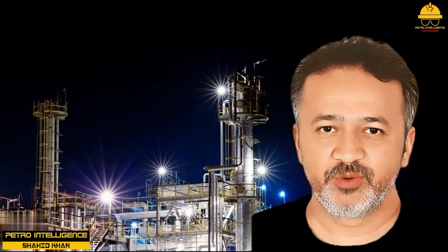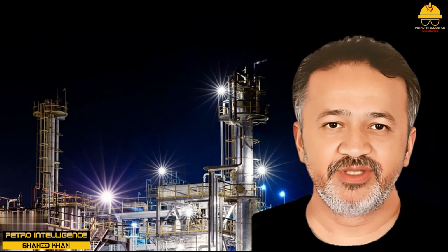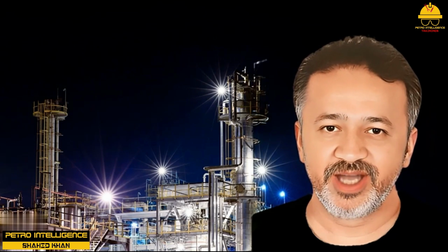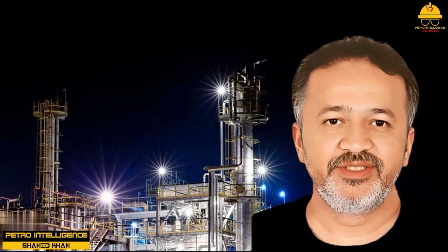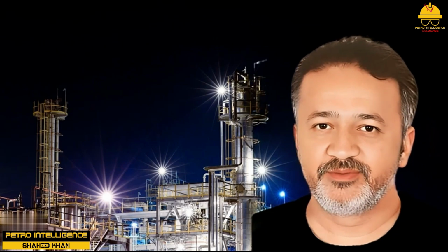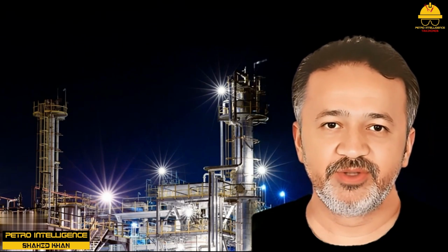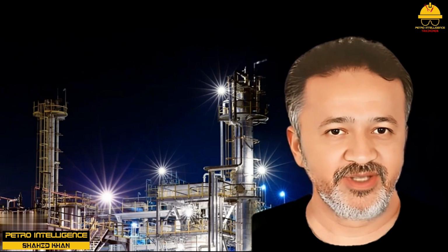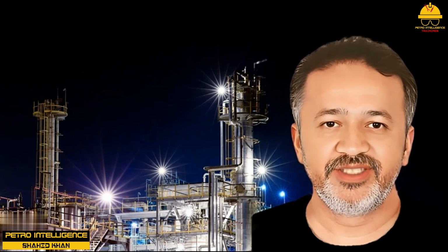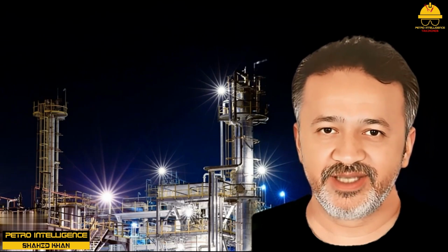Usually, any reactor or reaction system can have a set of conditions that could cause a hazardous situation if allowed to exist. Safety devices such as high-pressure relief valves and alarms, high-temperature alarms and emergency cooling, fire control systems, and toxic chemical detection systems are available for most hazardous conditions and should be installed as needed.